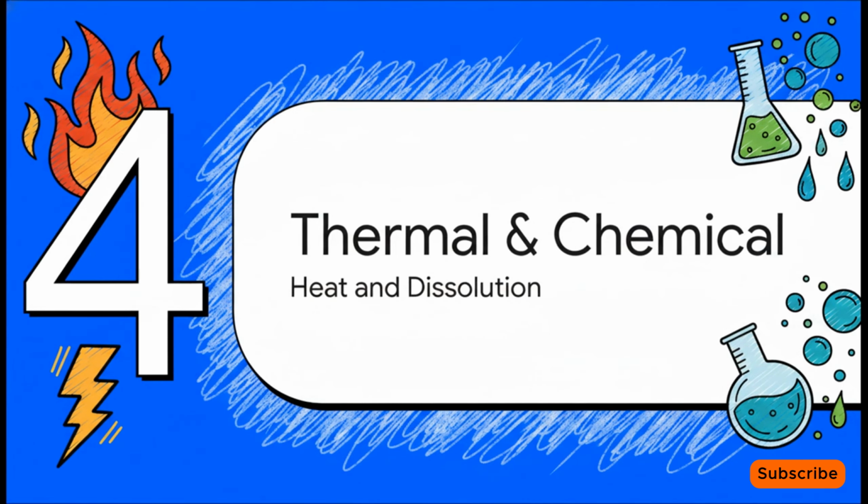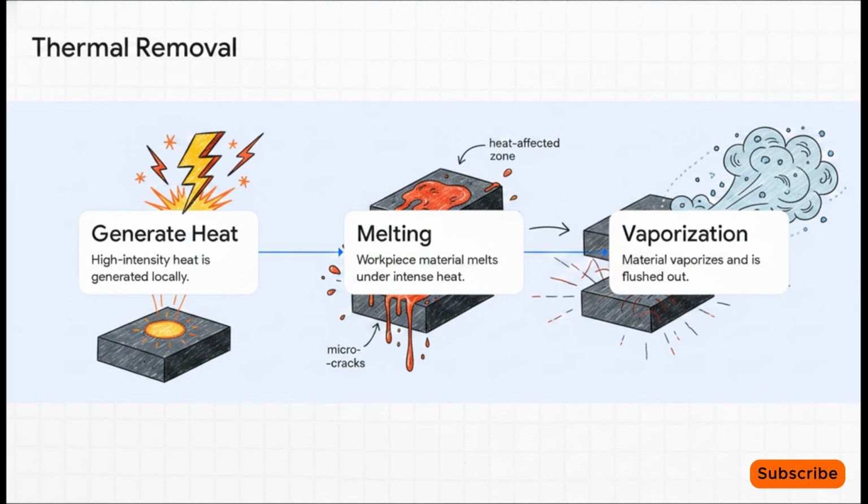All right, let's jump into section 4, thermal and electrochemical machining. This is all about extreme heat and dissolution. Moving way beyond physical impact, thermal processes use extreme energy to just outright melt and vaporize material. Electrical discharge machining, or EDM, uses electrical sparks to erode material, which is absolutely perfect for creating complex shapes in hardened steel molds. Electron beam machining, EBM, fires high-speed electrons in a vacuum for incredibly deep, narrow cuts.